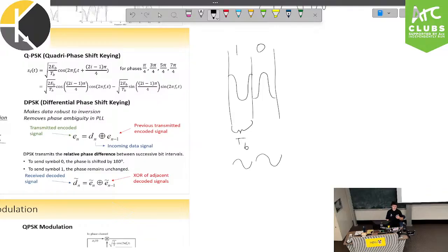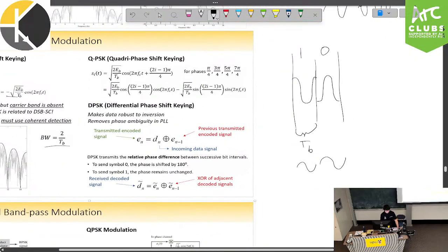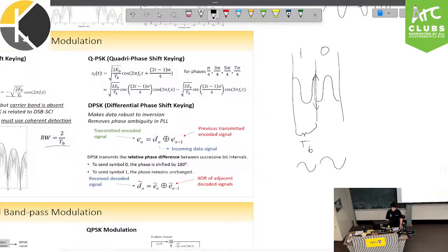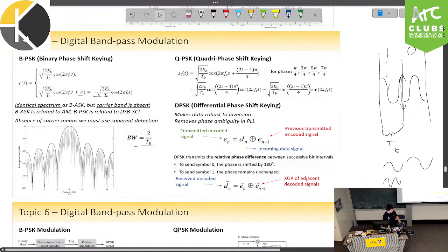However, it's not really going to observe the change very well, especially in here. We need to observe at a slightly higher frequency, and we can relate this a little bit more to sampling. If we go at twice the rate, we can see that, okay, here we have 1, here we have 2. It identifies, yes, there is a high here, yes, there is a low here. So that's one of the big advantages of bumping up our frequency. It lets us see things a bit more clearer, okay?